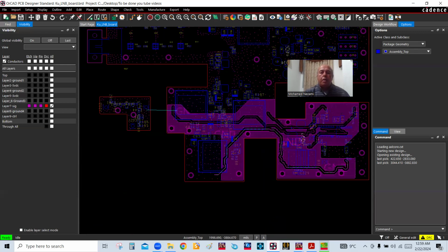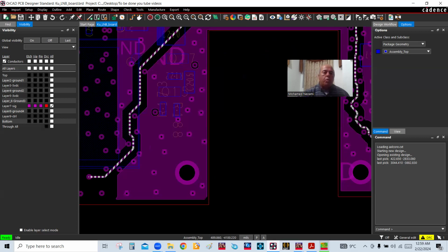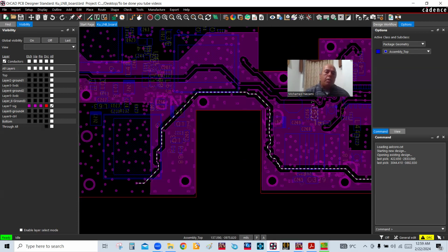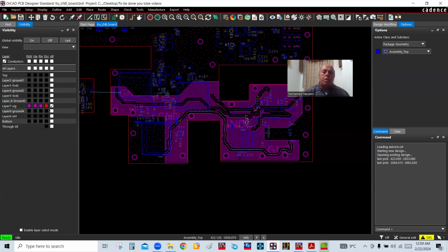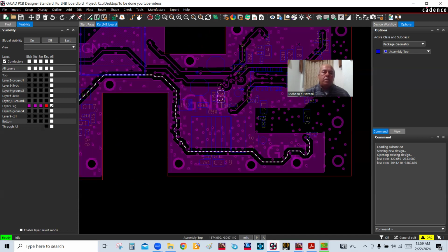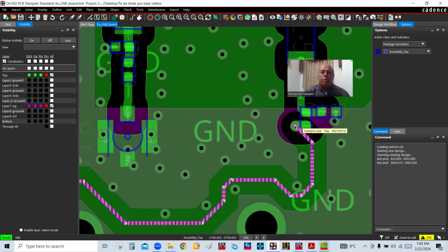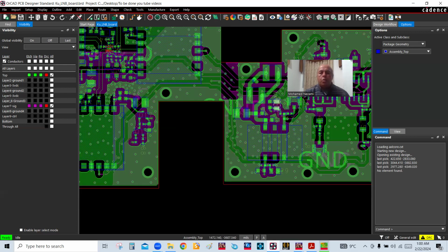And this here, if you calculate at a width of 8 mils, it turns out that you're going to get this width here, which is somewhere on the order of between 8 to 10 mils, and then it takes it back to this module, the phase lock loop module. So this is a critical trace. It involves a transition where you go from the top down to this layer here, the 7th layer. So this is strip line, which is critical. We want to sweep that as well.